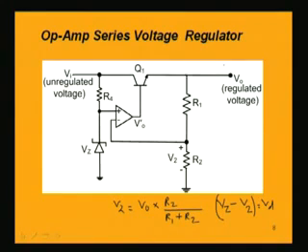That means now V0 will also be decreased. So from the whole analysis, we see that even though V0 is increasing, the regulator circuit is acting in such a way that finally V0 is decreased. That means the resulting outcome is that finally the output voltage V0 is maintained at a constant level.